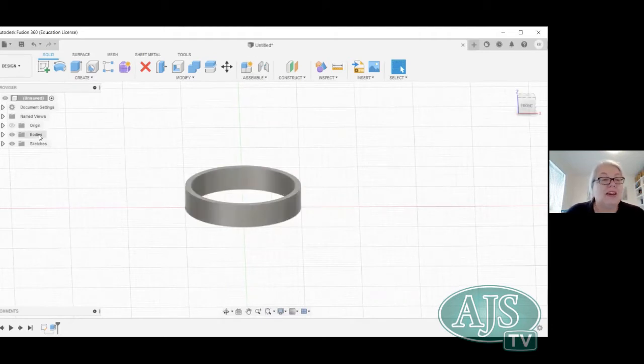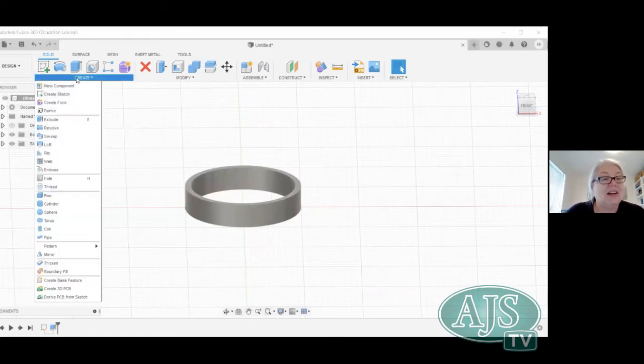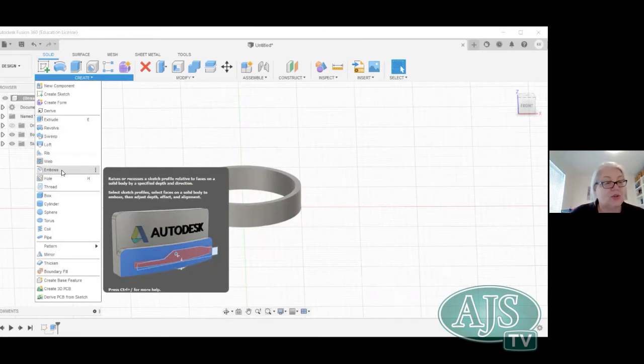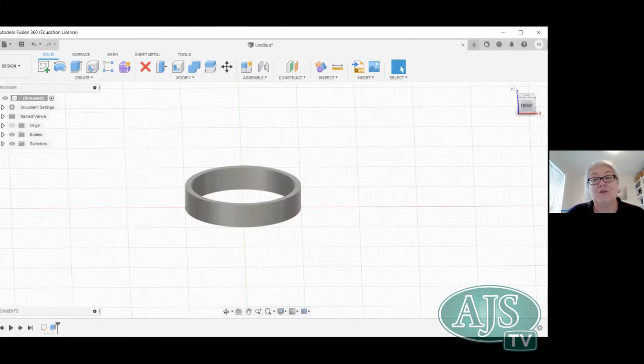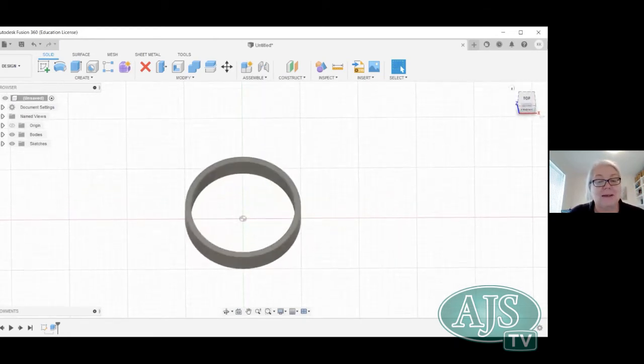The way that we've actually got in Fusion 360, there's a couple of different ways of doing text. So I'm going to go with the easiest. Now, what we've got in here, if you go into the Create menu once you've shut down your sketch dialog, is a little tool called the embossing tool. That's a relatively new thing that they've had. They've only had that for about a year. And it is massively useful, because the old way that we used to have to do it was we actually had to do it like sheet metal and unwind it and do a whole lot of far more complicated things. Now it's pretty easy peasy.